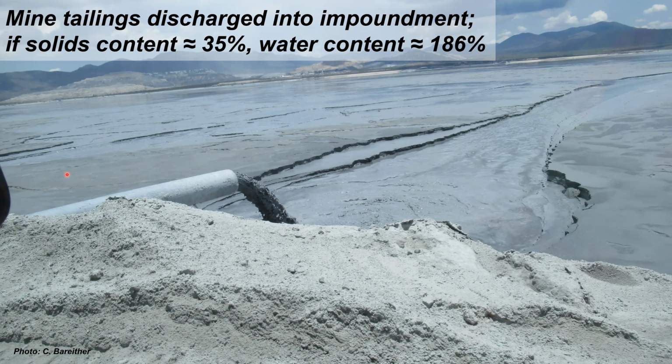So this is a very fluid material that's at first not going to behave much like soils. It's going to behave as a viscous fluid. And that's why we use viscosity rules and different mechanics to understand flow of these tailings through pipelines.